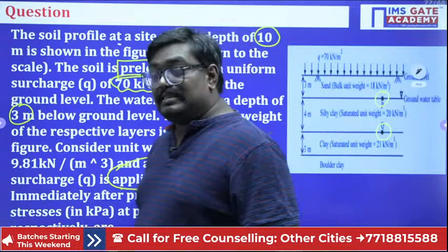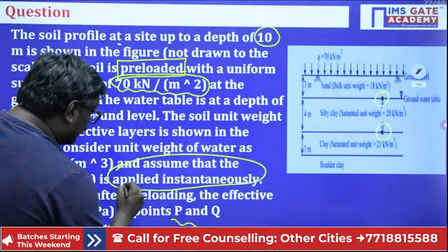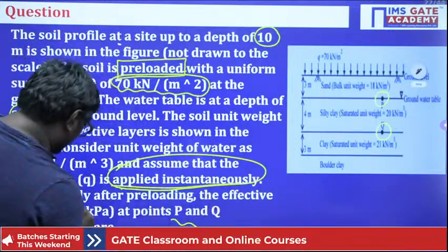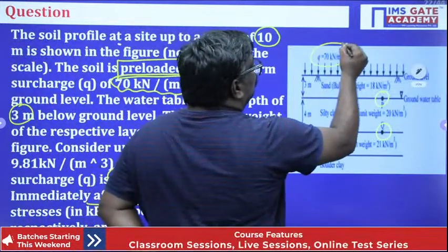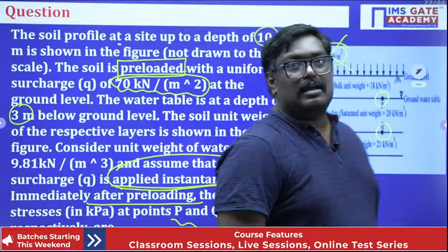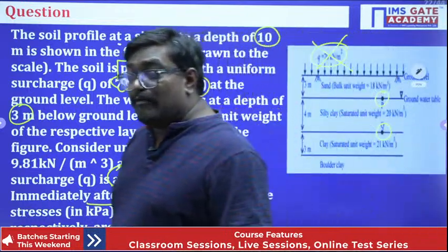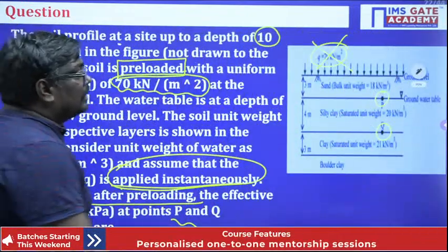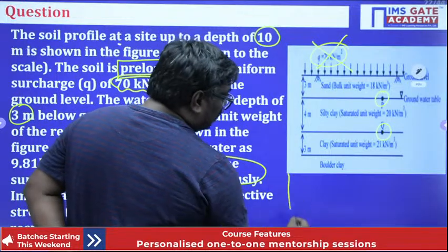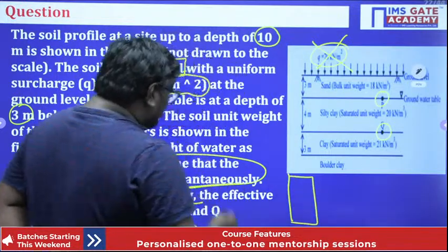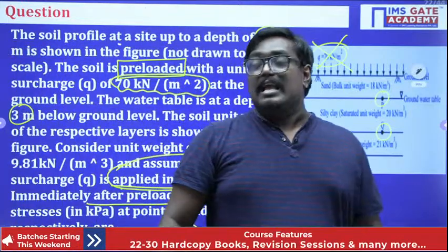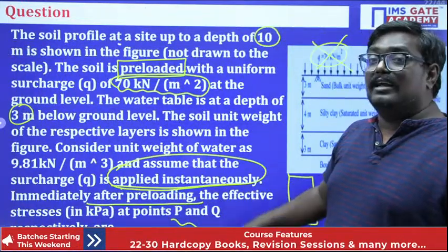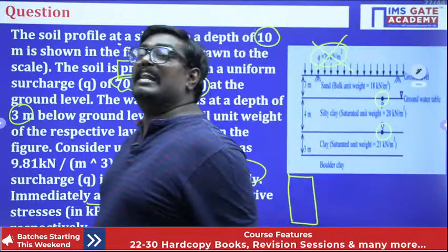Whenever it is applied instantly after preloading, the surcharge will not have any impact. I told you that whenever there is a surcharge loading, the stress will be uniform throughout the length. But as it is applied instantly after the preloading, it will not have any impact.